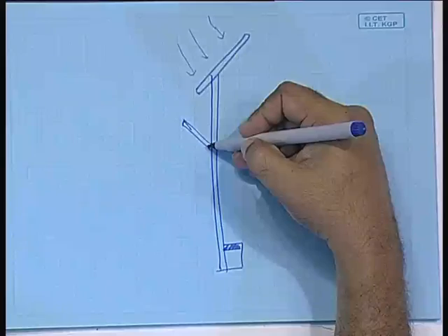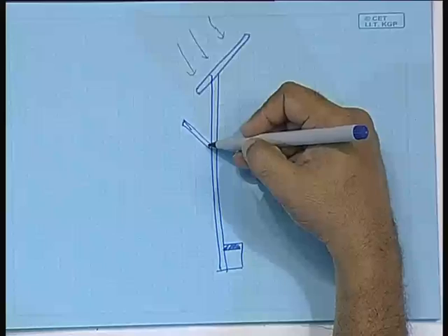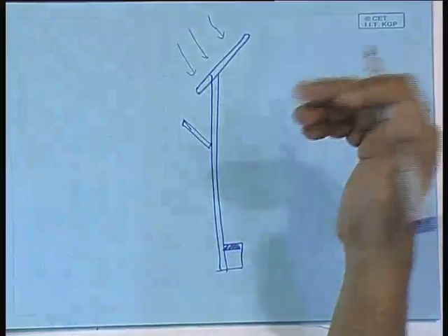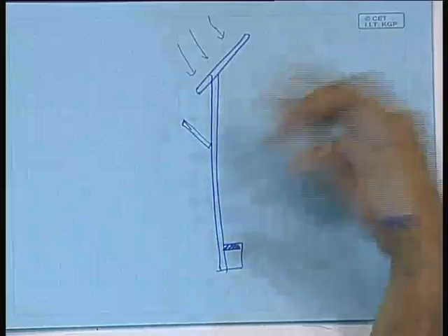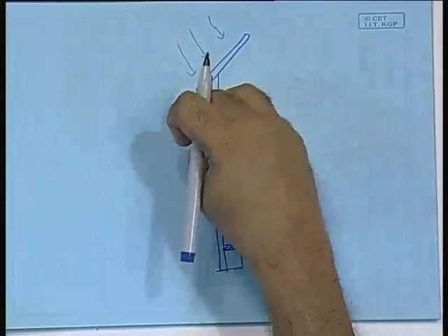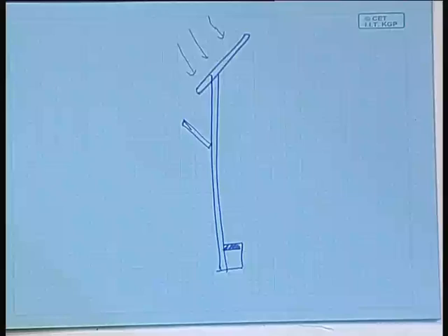There are two kinds available. Either you can use it simply as DC, as tube lights also work in DC, I suppose you know. But for that the voltage has to be boosted up to the level that is necessary for the tube light, and that is what is done by a small power electronic circuitry stationed here, or it can be converted to AC and the tube light is used.